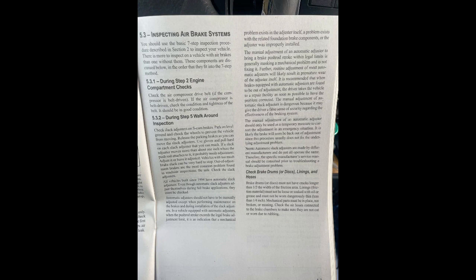All vehicles built since 1994 have automatic slack adjusters. Even though automatic slack adjusters adjust themselves during full brake applications, they must be checked. Automatic adjusters should not have to be manually adjusted except when performing maintenance on the brakes and during installation of the slack adjusters. In a vehicle equipped with automatic adjusters, when the pushrod stroke exceeds the legal brake adjustment limit,